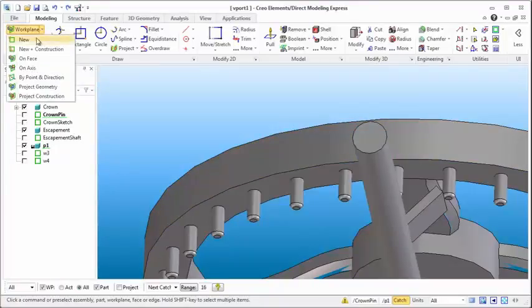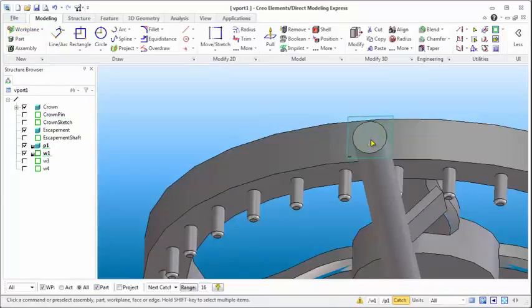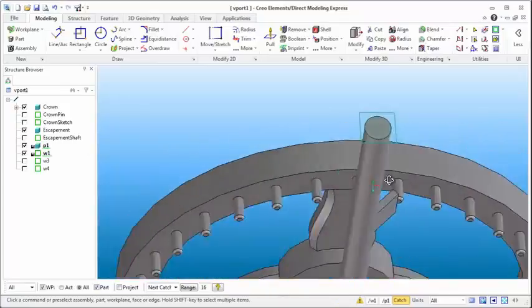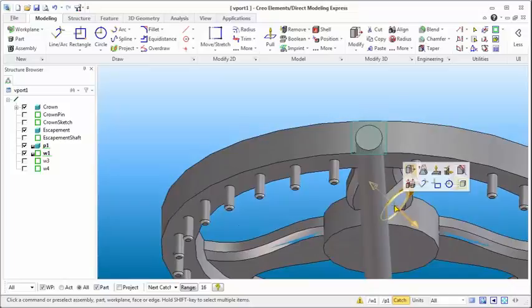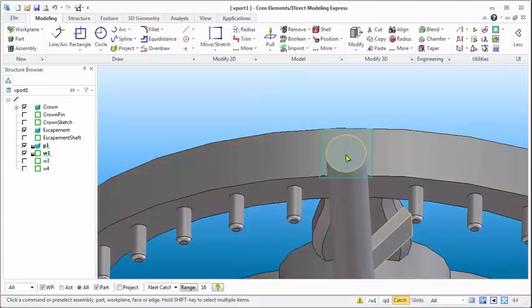So the best thing to do on this is that you go new work plane on a face. We're going to check on that face, and you'll notice that we're still active in this part one that we're going to be using to create the pendulum. So that way we stay out of some of that geometry, and we don't end up modifying something we didn't want to modify in the first place and having to hit Control Z and redo everything.